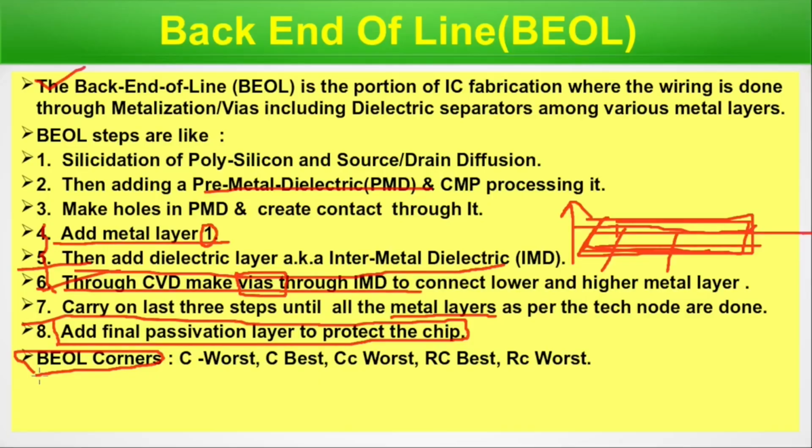I'm going to tell here in short: parameters of semiconductor fabrication are generally statistically distributed because it's not an ideal process. It's the real world. Not all two devices have all the properties the same. Some variation occurs in length, width, oxide thickness and all. Since the ICs we fabricate on a wafer are not identical, we must judge their merit within a range of data, not one particular data point.